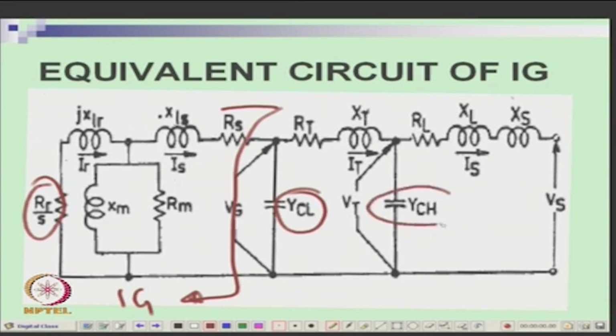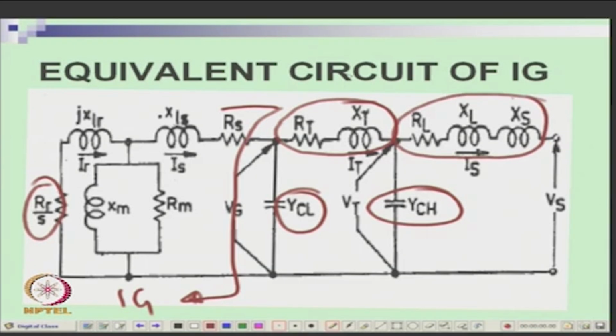You can have it on both sides or one side depending upon the plant. Then you must write the transformer impedance. Transformer also has resistance and leakage reactance. Then the transmission line also has its reactances, and the grid also has a system reactance. There is nothing like an ideal grid. A grid is a voltage source with its own reactance. Even a battery you cannot call an ideal source, you put some resistance to represent it. So, your system study will have all these things.